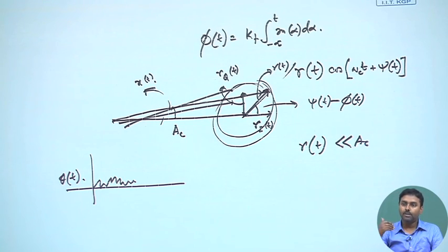If the noise amplitude is very high, then whenever you are demodulating FM, you will see those clicking sounds randomly happening in between. That is termed as FM click noise. We will discuss more on these things in the next class, and then we will also talk about the threshold effect. Okay, thank you.